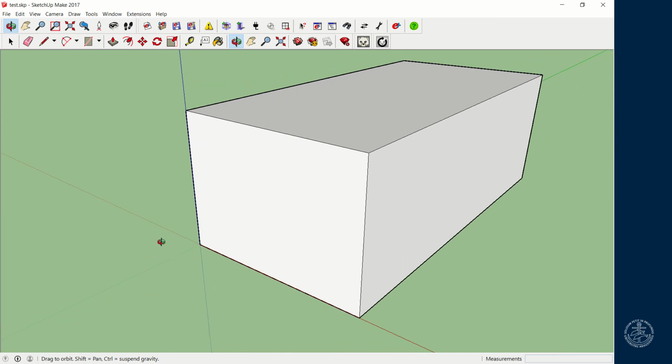And the definition here in ICEbear is that this dotted green axis in SketchUp is south direction. So right now this surface here is vertical and facing south. So I want a south-facing window, so I draw a rectangle here on this surface. If I wanted it to the north, it would of course be on the other side. I can also rotate the room just using the standard commands in SketchUp.